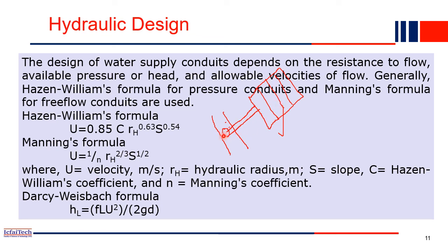So for that purpose, you know how much discharge means, how much quantity you have to distribute, means this Q value you know. And now you can find out what is the R value, because n is anyway constant, that is the maintenance constant, you will get it. S is the slope, right? What is the slope from intake to this water treatment plant? How much is the slope, ground slope? That also we can measure. So you know S, you know the constant, you know Q, easily you can find it. What is R, means the hydraulic radius, right? What is the radius of this pipe, you can easily compute. So like that, using these formulas, basically we can compute the different design parameters for the calculation purpose.